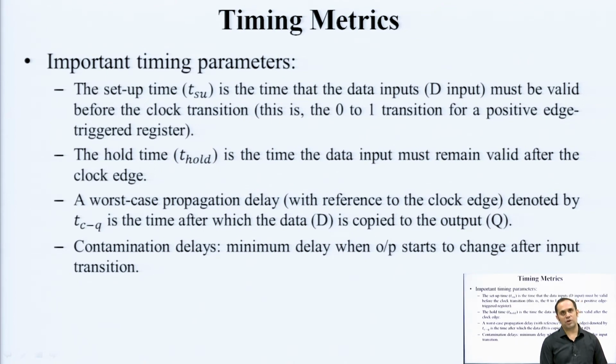So, before the clock triggers, the input should be remaining there, valid for some time, that is your setup time. Once the trigger has happened, again the input should remain valid, should remain available, so that the data transition is considered reliable. That is known as hold time.